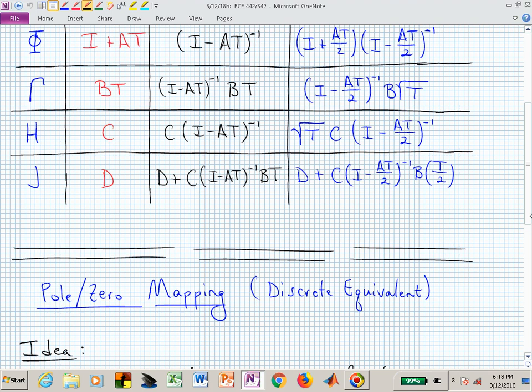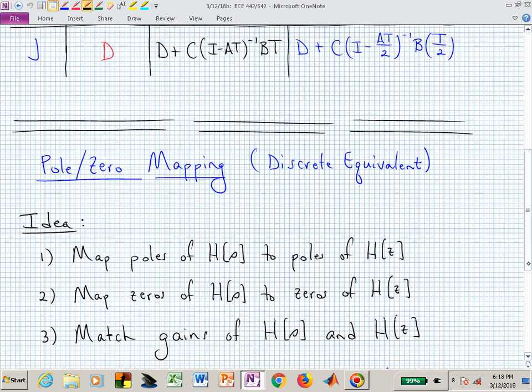So the hold device is really converting this sequence of numbers into an analog or a continuous waveform. And we're doing it via a zero order hold, so we're just holding it constant. So the hold device is really introducing some dynamics because it's changing this sequence of numbers into a continuous signal. And we integrate or incorporate that into the discrete time representation of that model.